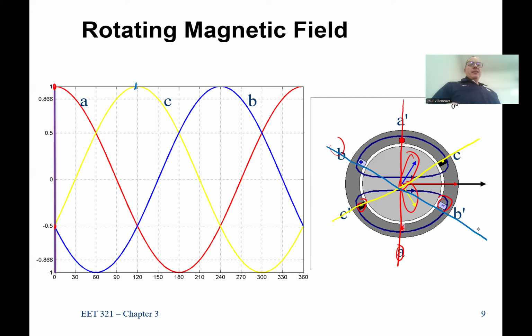It's C, and then it's B. So not the windings, but the source is ACB. Remember, the motor windings or the machine windings are just hunks of copper. You actually run current from each phase how you specify it. So the machine itself is not ACB. That's the source.